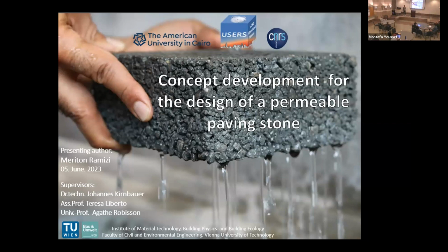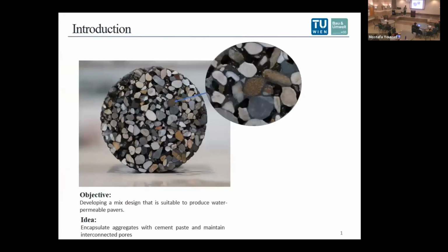Today, I would like to share with you the work we have done for my master thesis, which is about water permeable pavers. The aim of this work was to optimize a mix design suitable to produce water permeable pavers by adding a cement paste which is fluid enough to cover the surface of the grains and binds them together while not flowing during the manufacturing process. The main challenge was to maintain the connectivity of the voids and retain sufficient water permeability and mechanical properties.